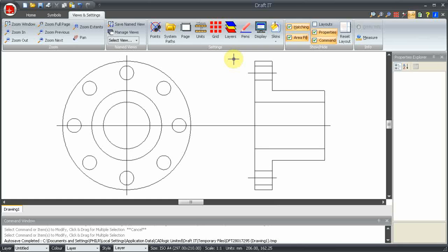For example, on a building plan, the walls could be on one layer, whilst you could draw all of the electrical information on another layer and all of the plumbing on yet another. Thus, by turning off and on certain layers, one drawing can provide multiple uses. There is no depth between the layers. Think of them as transparent sheets, which, when laid on top of each other, form the drawing.